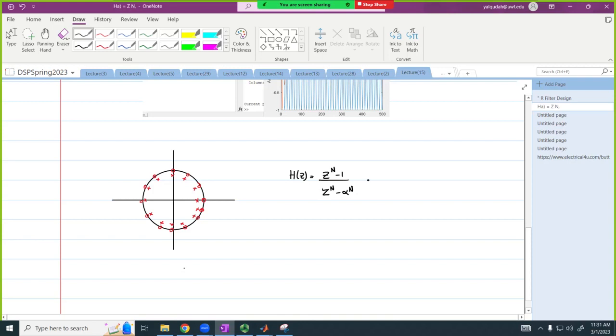We can just multiply by z minus alpha divided by z minus 1. Make sense? If I divide by z minus 1, then the z minus 1 that was the 0 in here is going to be gone. Z minus alpha, the pole that was here, is going to be gone. Is that clear? Everybody? Anybody understood this? Don't be shy. Not really?